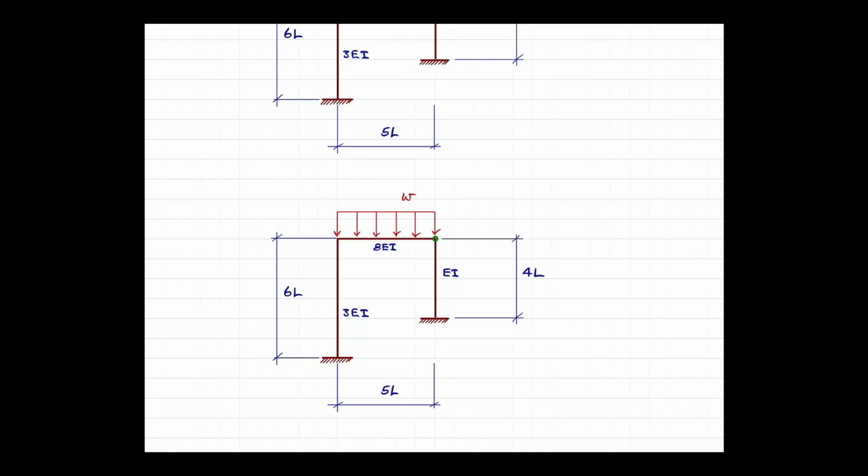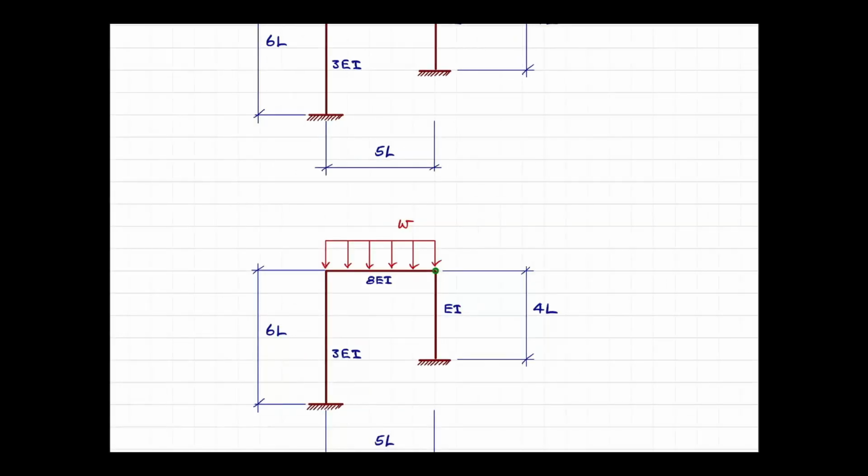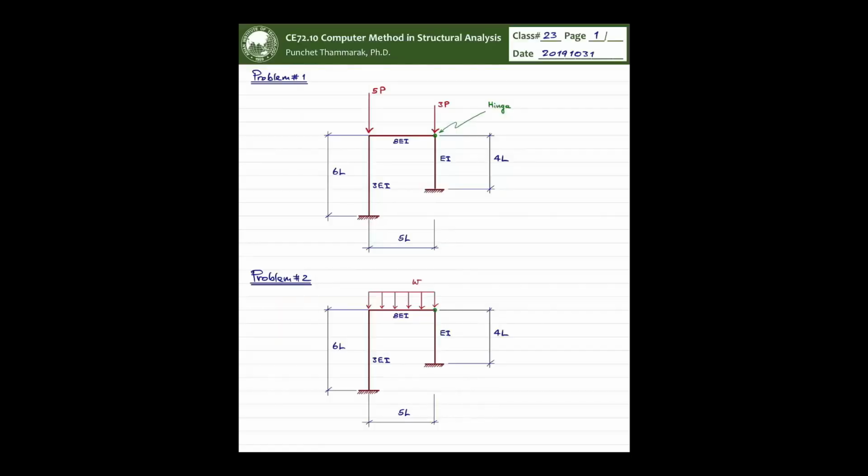Maybe this is the best way because we can share the same structure, so we don't need to cast the stiffness matrix for the whole structure too many times. Use of the geometric stiffness matrix, we need to enable the deformation. We need to be able to pick up the deformation which is caused by the second order moment.